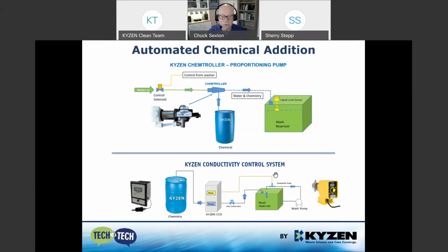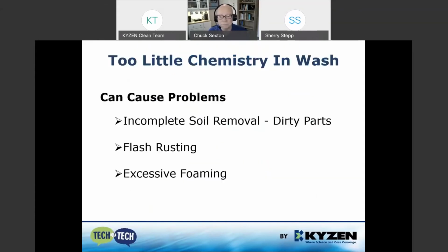The system shown on the bottom is a bit more sophisticated. Here we're actually measuring the concentration in the wash stage or rinse stage by measuring conductivity, sending a signal to a metering pump, and adding the chemistry accordingly.